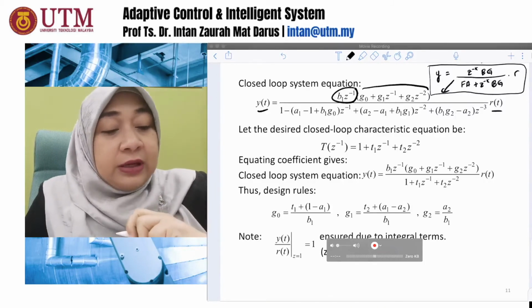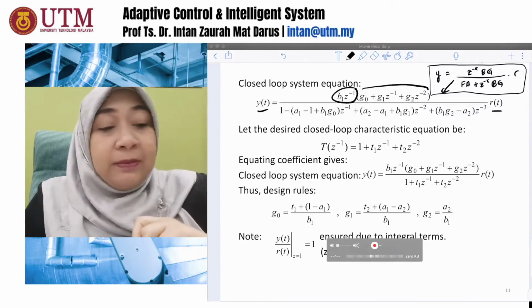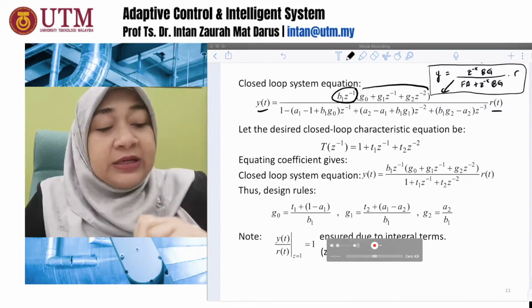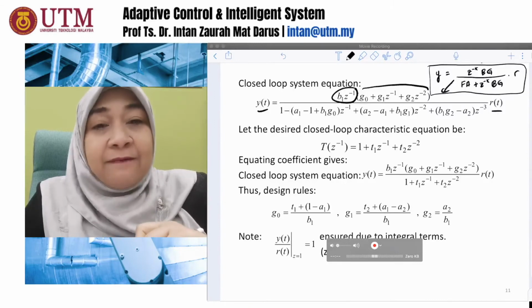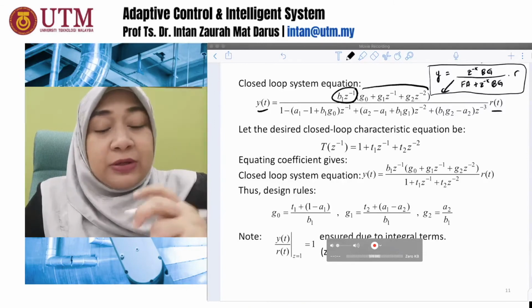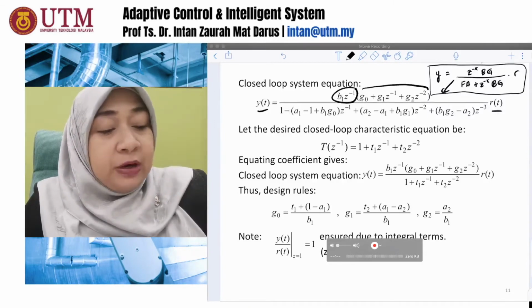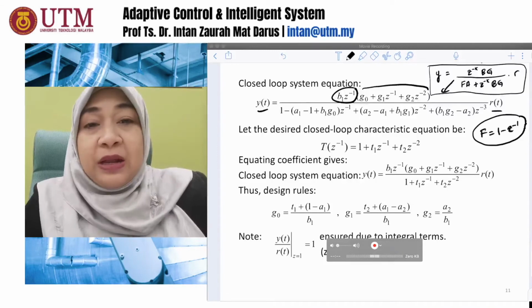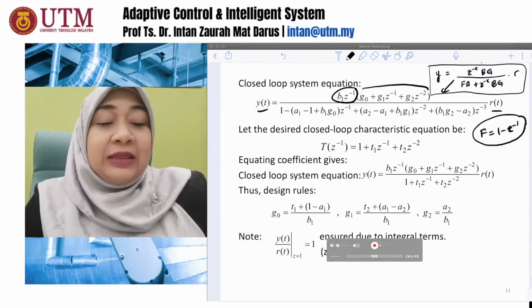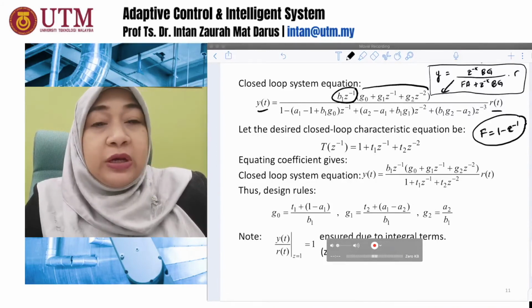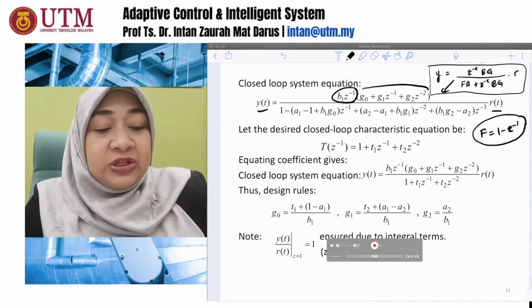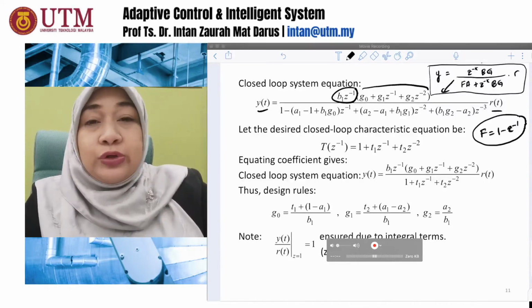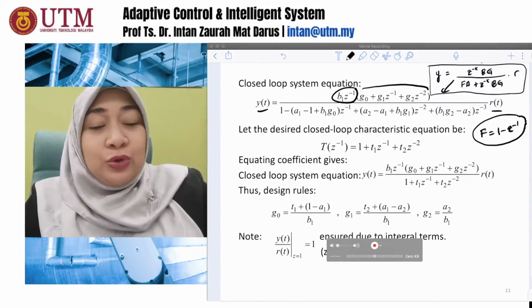At the bottom here I have one minus, I have actually expanded the value from f multiplied by a, because I know, remember for the polynomial f we straight away use 1 minus z minus 1, isn't it? So that needs to be multiplied with your polynomial a, and then you need to add the polynomial b multiplied by g. So that will give you this huge equation that I've shown you in this slide here.